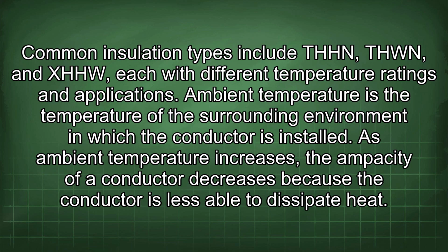Ambient temperature is the temperature of the surrounding environment in which the conductor is installed. As ambient temperature increases, the ampacity of a conductor decreases because the conductor is less able to dissipate heat.